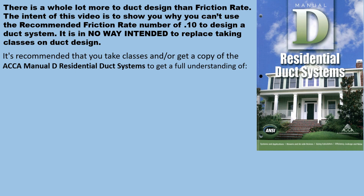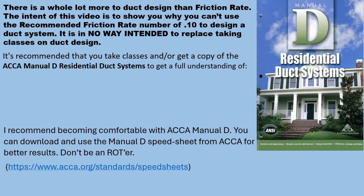It's recommended that you take classes and/or get a copy of the ACCA Manual D residential duct systems to get a full understanding of basic rules of duct design, do's and don'ts of duct fittings, velocity pressure's role in duct design, the equivalent length and poor performance of return bays, and much more.